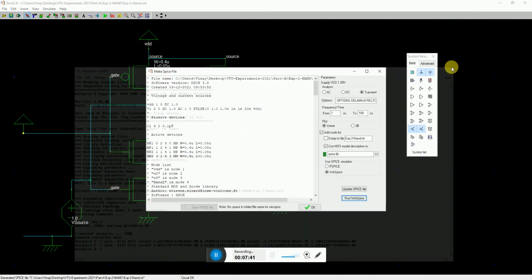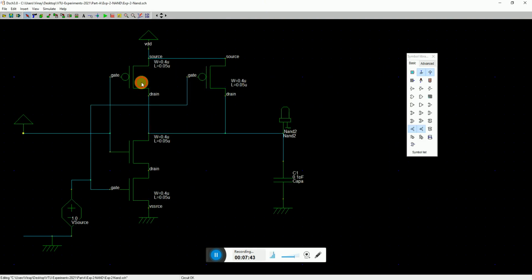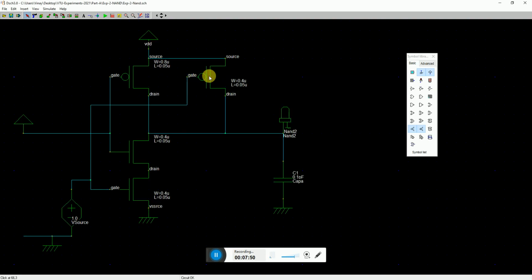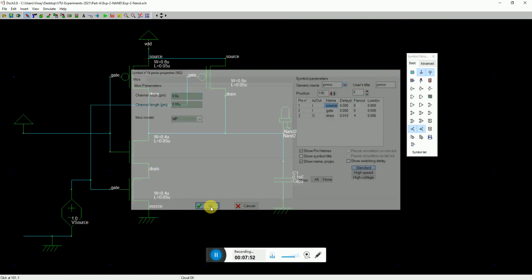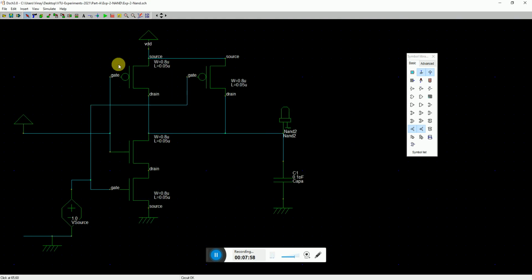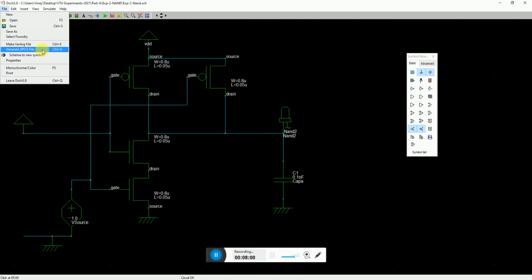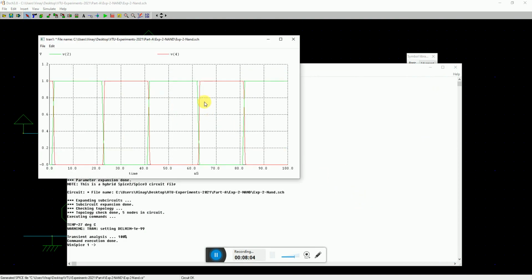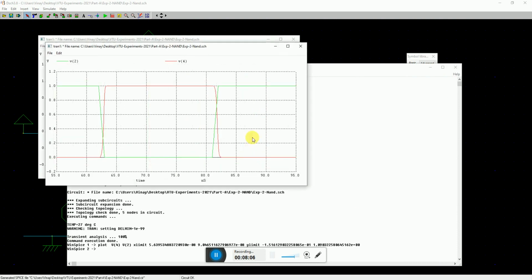So here quickly I just change the width to 2x, that is 0.8. So I just copy this 0.8 micrometer and replace this in the widths of all the transistors. I'm not playing with the length. And say file, generate spice. So here we see that the delays have reduced. We zoom up in one of the blocks.